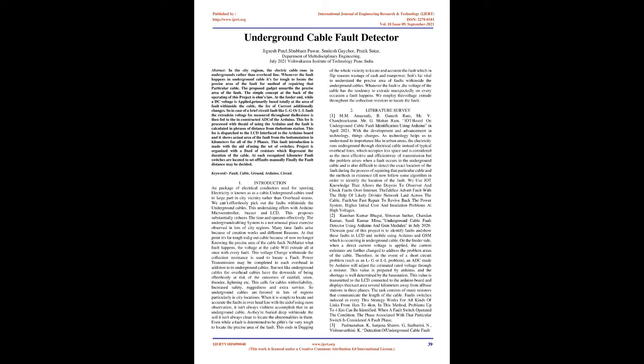The simple concept behind the working of this project is Ohm's law. At the feeder end, when a DC voltage is applied, the current changes based on the location of the fault in the cable. So in case of a short circuit fault like an LG or LL fault, the change in voltage measured across the series resistors is then fed to the inbuilt ADC of the Arduino.